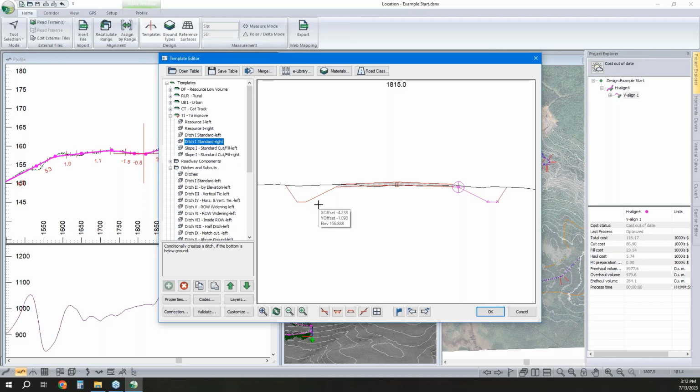So aside from that nice functionality of just giving us somewhere to intercept flow and keep that away from our road top, adding a ditch does another thing for us, and that is it creates this extra cut. So we can just take the cut material out of there and flop it over to build up our subgrade,